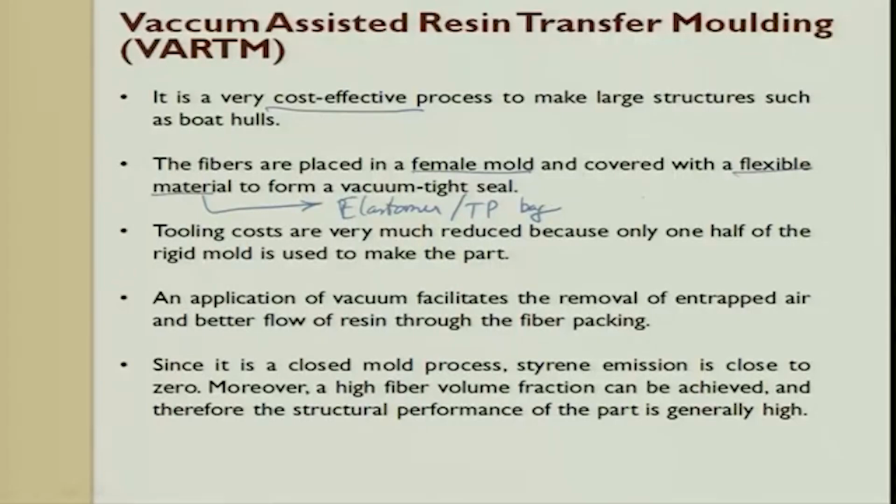So, what you do is you place the preform, and then you place the bag. So, this is the reinforcement, this is the seal that you make, and this is the vacuum bag. Now you put this airtight bag, and this is a sealing. Sealing is nothing but a sealant stopping you can put, or a tape you can put, whatever it is, and then you start sucking vacuum.